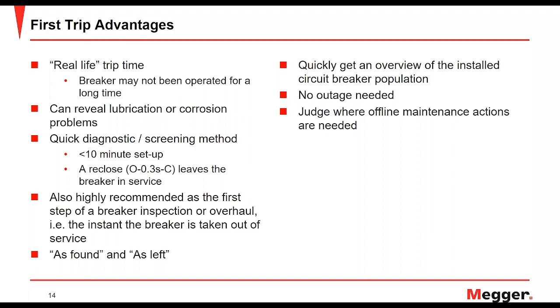Also, it's highly recommended to always do a first trip before taking the breaker out of service for a half or full overhaul, to see what that first trip condition will look like.